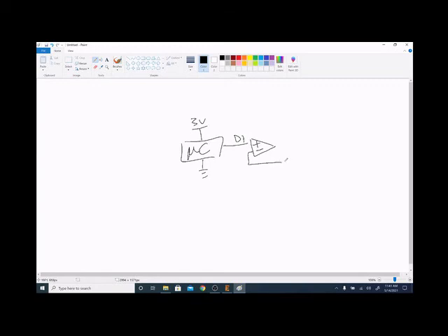We're going to set this up as a constant current supply. So we have our current limiting resistor down there. We have a transistor up here, and that's an N-type transistor. And then we're going to have our 2 LEDs that we want to drive sitting above the whole thing. And those will be powered by a 6-volt supply, as well as our op-amp here. The op-amp is going in single supply mode, so that'll be at 0 on the negative supply. And then this transistor that we're using is the 2N3904 transistor. And that's our whole circuit.